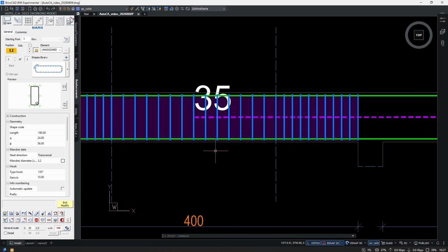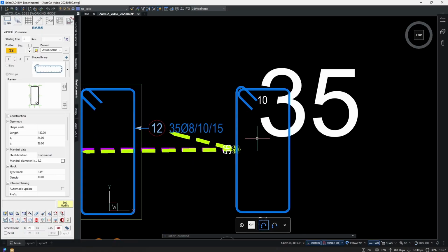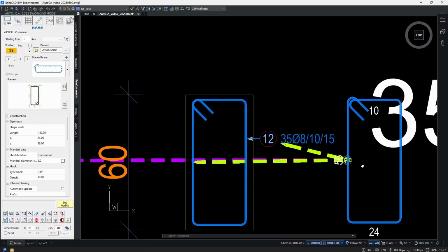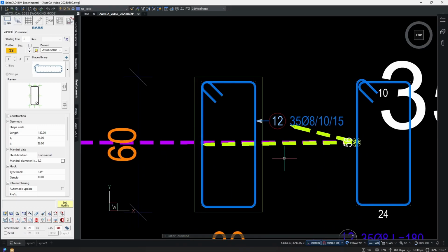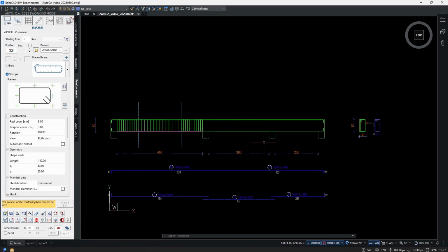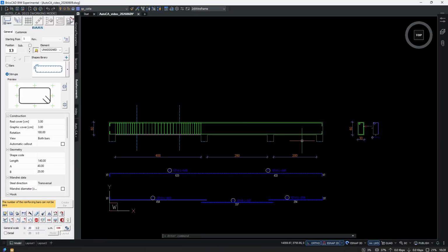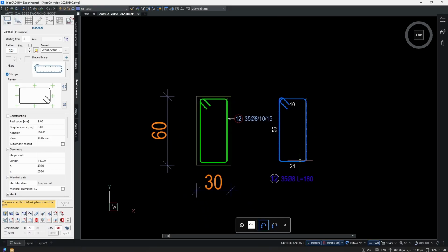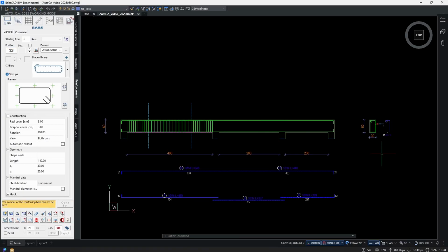And now we see that from this distribution comes the 35 bar number. The callout is also linked to this bar, and the inside bar is linked as well. So this is the correct way to use the program logic to count bars. Yes, there's the possibility to insert bar number by hand, but it's always easier to let the program do the hard work. And most of the time, it's more precise also.